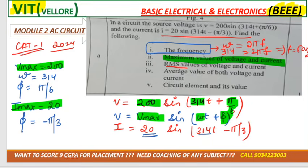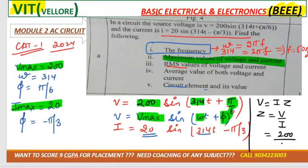Now in the next part they ask you the circuit element, whether it's a combination of R, L and C. See how can we get it? As you know, V is equal to how much? IZ. So Z is how much? V over I. V is 200, I is 20, so Z is 10. Understood?